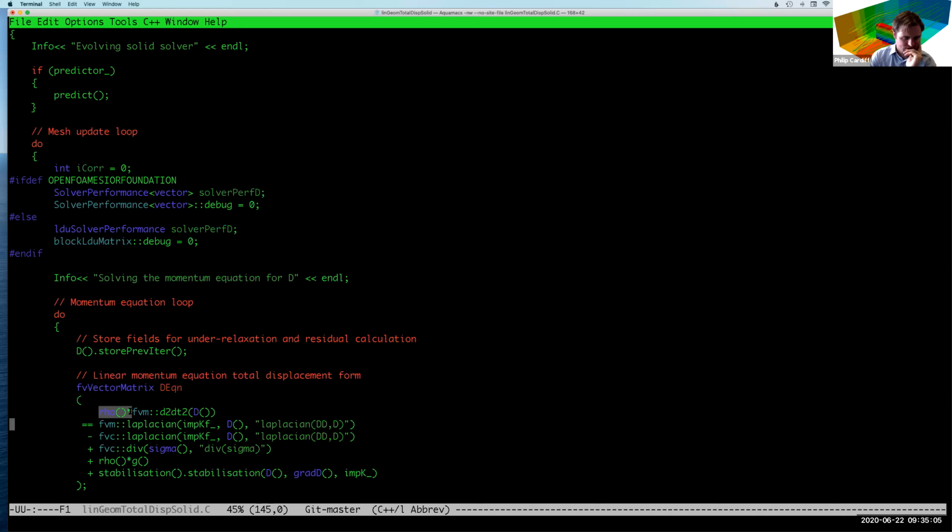So this is mass times acceleration per unit volume on the left-hand side. On the right-hand side, we have the sum of the surface forces and gravity. And then we also add a stabilization term, or the option to add one, like Rhie-Chow or one of those techniques, just so we don't get checkerboarding, which OpenFOAM does in many cases, or is inspired by.